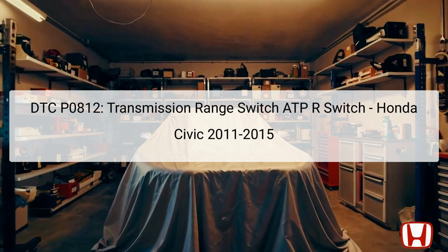An essential point to note before proceeding with any troubleshooting is to record all freeze data and conduct a thorough review of the general troubleshooting information using the Honda Diagnostic System, HDS. This systematic approach ensures that the technician is briefed on the latest diagnostics and helps in pinpointing the electrical failures leading to the code.